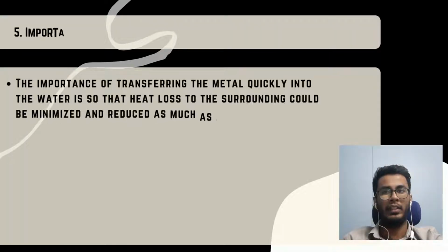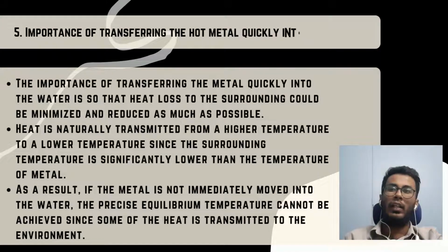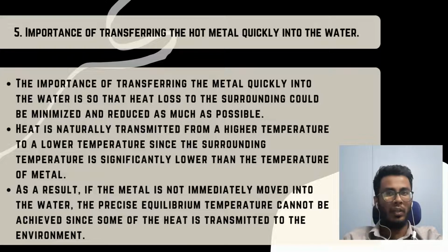The last discussion is the importance of transferring the hot metal quickly into the water. The importance of transferring the metal quickly into the water is so that the heat loss to the surroundings can be minimized and reduced as much as possible. Heat is naturally transmitted from a higher temperature to a lower temperature, since the surrounding temperature is significantly lower than the temperature of the metal. As a result, if the metal is not immediately moved into the water, the precise equilibrium temperature cannot be achieved since some of the heat is transmitted to the environment.